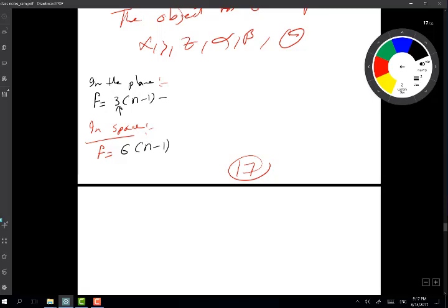Now go back to the plane. I have every r deducted 2. Why does every r deduct 2? Because r allows for 1 degree of freedom, which is rotation. So it has to deduct 2 from the 3. In space, it will have to deduct 5, correct? Same for p, so this will be 5p. Now h will be exactly h here.